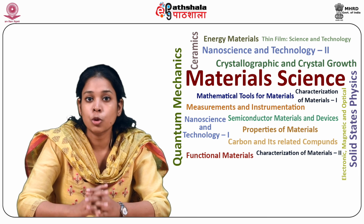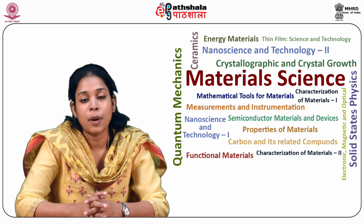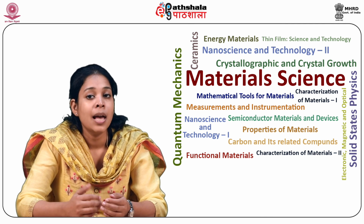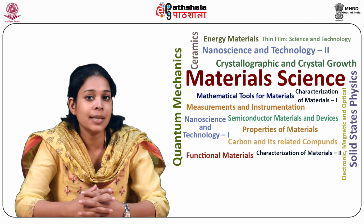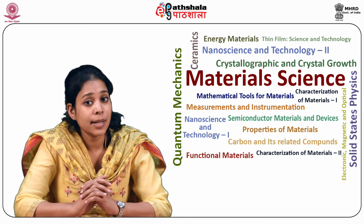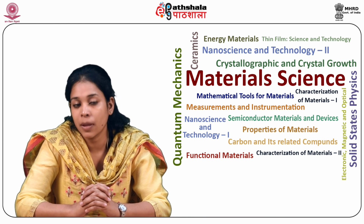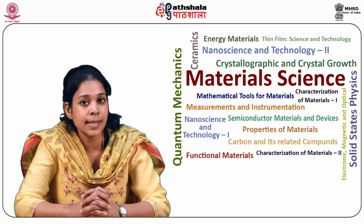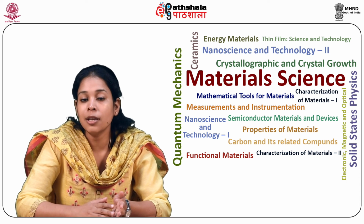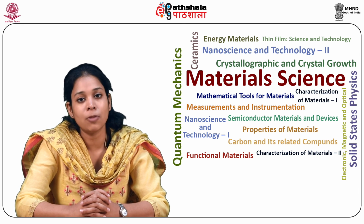The tetragonal to monoclinic transformation results in an increase in volume of about 4 to 6% and a shear strain of about 1 to 2%, leading to pure zirconia body disintegration on cooling after sintering. So pure zirconia can therefore not be used as a sintered part in the pure form. Zirconium oxide, that is ZrO2, has a cubic fluorite structure, and the tetragonal and monoclinic structures are obtained by distortion of the cubic structure.